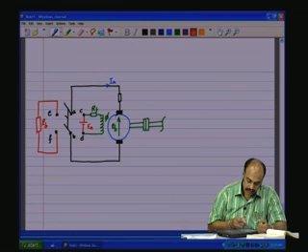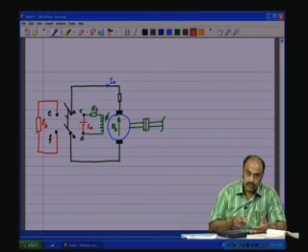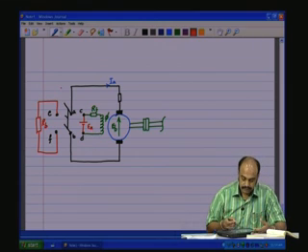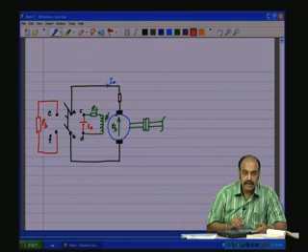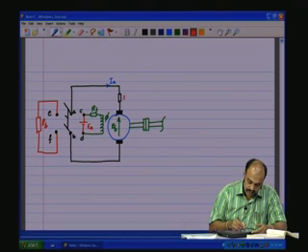Now, during braking, we open the switch and connect it to E and F, which means A and E are short, B and F are short, which means now the whole system is acting like a generator. The inertia is rotating the shaft, there is a generated voltage EB, which is seen as a voltage across the terminals of the motor and applied to a load RB.